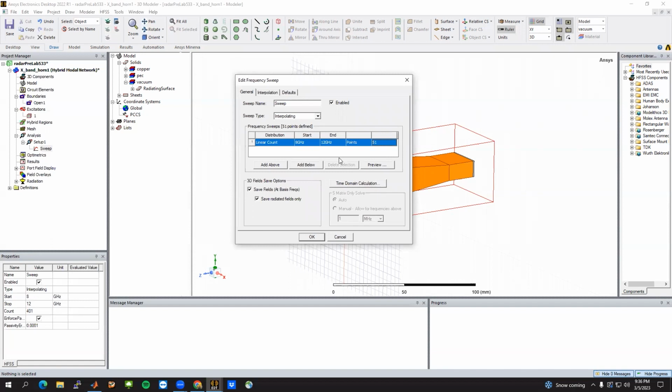That should be enough for the imaging that we need to do right now. But keep in mind that the number of points determines your aliasing free range. So if you have targets that are further out, or if you have some reflections that can get aliased into your target range, you may want to use more points. But in this case, since it's a simulation software, there aren't really any targets beyond our target of interest. So I'm just using 51 points.